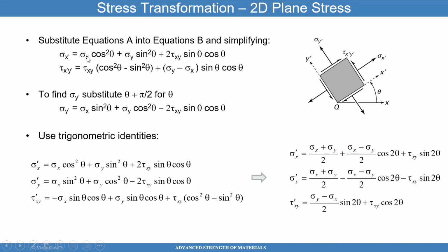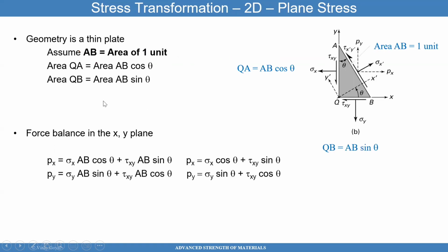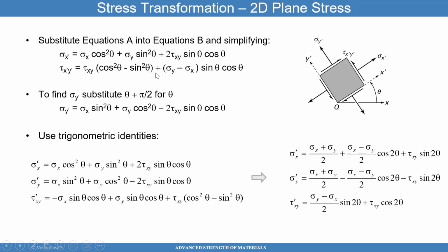I can relate that to the stresses that are acting on that square that we saw here, right? So again, remember, these are the stresses I know, but I'm looking at what is the stress in this inclined plane. And I want to look at the normal to that surface and tangential to that surface. These are the values I'm looking for. So I'm trying to figure out how to relate this to the original values that were provided on stress states. And I'm able to achieve this formula here, which I will not make you memorize, but you should know how it was derived at least and have it with you.